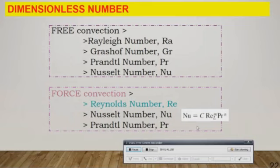If, let's say, you go through any other references, for example, myself, I use Yunus Cengel's references, there are different equations for different geometrical shapes. So for that, I will only introduce the general one, which is this one. The Nusselt number is given by the coefficient C, Reynolds number to the power of m, and then the Prandtl number to the power of n. This C coefficient will very much depend on the geometrical shape.